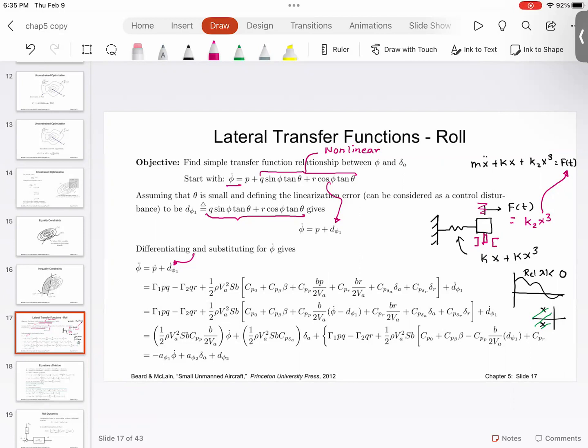All that big term, I'm replacing this as dp2. dp2 consists of dp1 dot and the nonlinear terms that came into existence after substituting value for P dot. Everyone understood this? Same thing. Grab those terms together and call it a linear term. Everyone understood this? Now, you can look at this equation and say, wow, this equation is linear, which means I can take a transfer function. Problem solved.